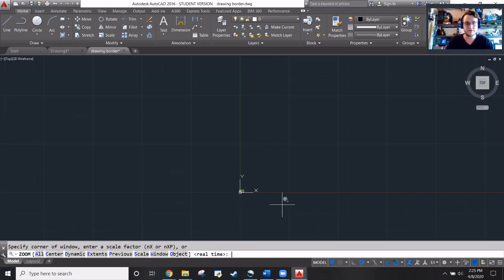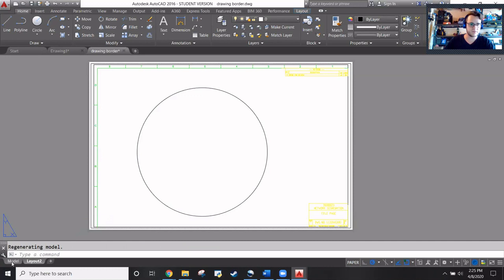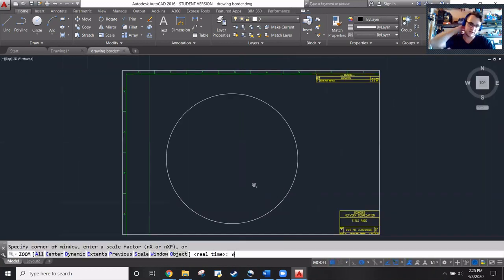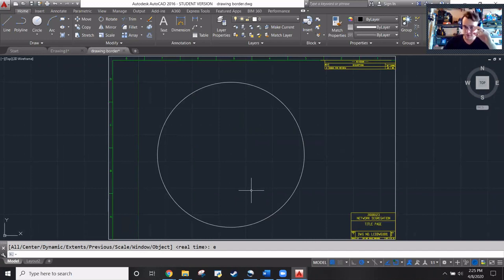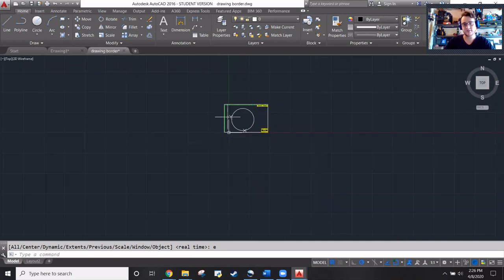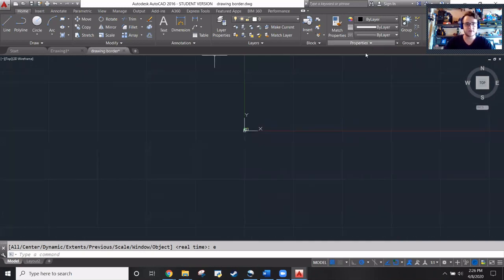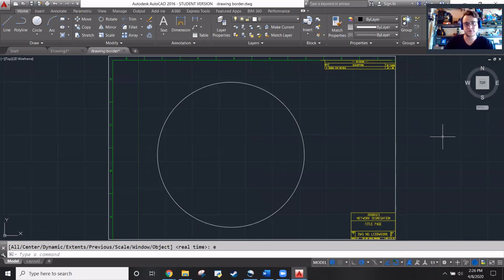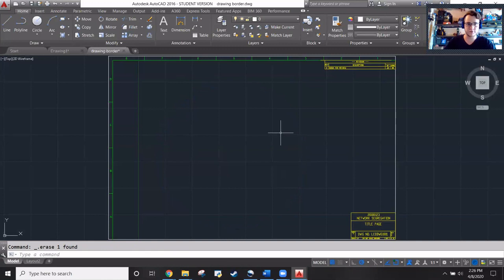So you can also use the zoom, so go to the model space. We're going to work in here now. You can also use the zoom extents command in model space. It works the same way. And that's usually useful if you're zoomed way out like I was: instead of trying to figure out where your stuff is, you can just zoom into it real quick. It's way easier. Its size is nice. Okay, so kill that circle. We don't need that anymore.